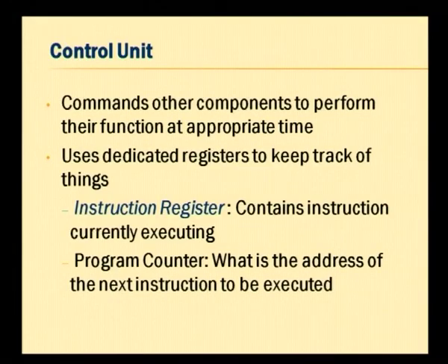One is the instruction register and one is called the program counter. Okay. Since we call it a program counter, you can see that a counter typically will be something which is counting, right. So, this would typically be counting and keeping track of the next address, the address at which the next instruction is located. An instruction register, on the other hand, will have the instruction that is to be executed, and based on the instruction, right, the control unit will be able to produce the right commands and give the correct control signals to the various devices that we talked about.